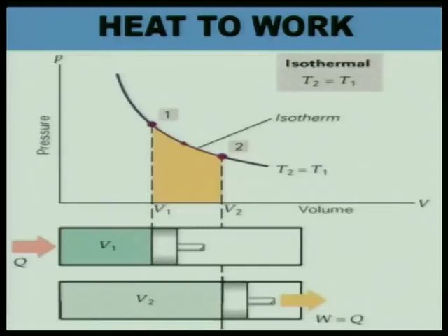The temperature between T2 and T1 is constant. If this type of heat addition process is there, the probability of conversion of heat into work becomes maximum. This type of process is a reversible process, and when this process happens inside the cylinder during heat addition, 100% conversion of heat into work is possible. We want to achieve this type of process, particularly when heat addition is taking place. So again, it is a dream, it is hypothetical. In actual engines, this type of heat addition is not possible at all.